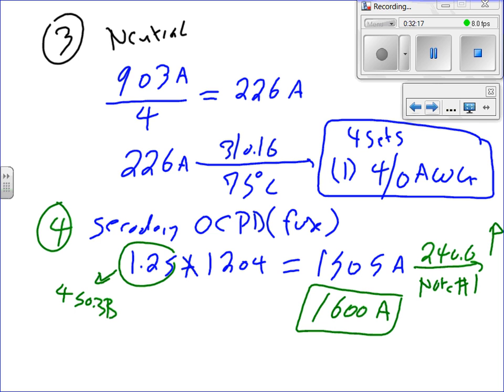If it's a circuit breaker, you can adjust it to 1500, because it's a big jump, 100 amp. If it's a fuse, you can't. For all practical calculation, that's what you're going to stick with.